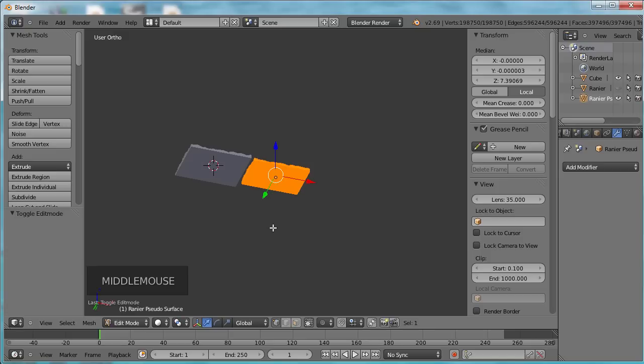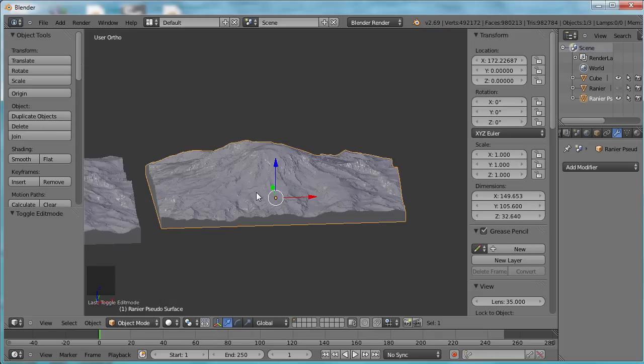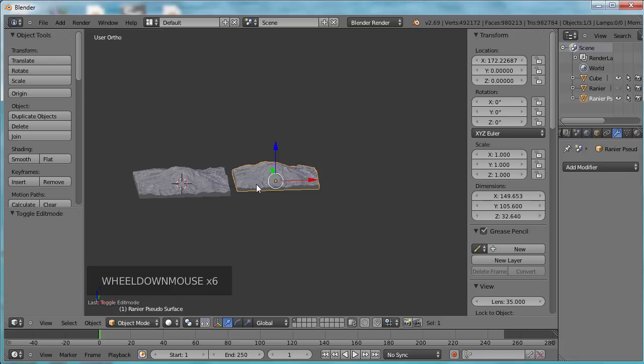Now, that said, your 3D printer and your slicer software probably don't care. You could send either of these files to them and you really wouldn't notice a difference in performance. Where you would notice a difference is if you were uploading to a service like Shapeways, which has a limit to how big a file can be, or a limit to how many vertices or how many polys a file can have. You don't want to waste your polys on the bottom of your element there. It just doesn't make sense. So learn to do it with Booleans in Blender is my advice.